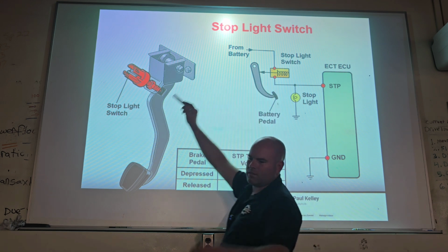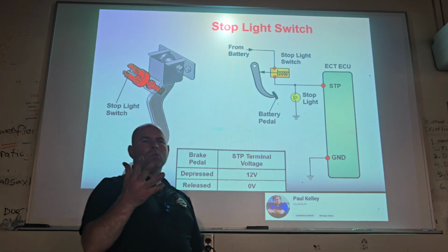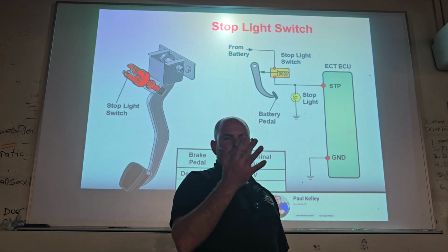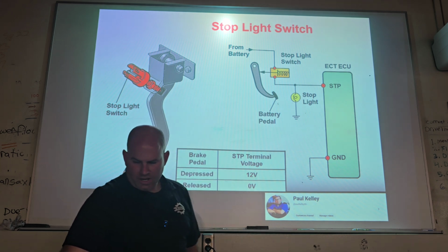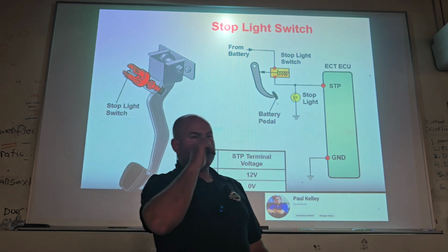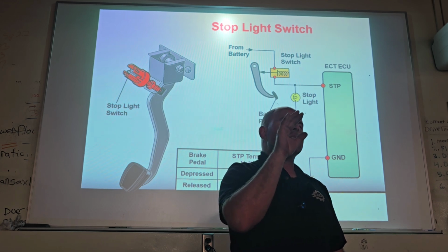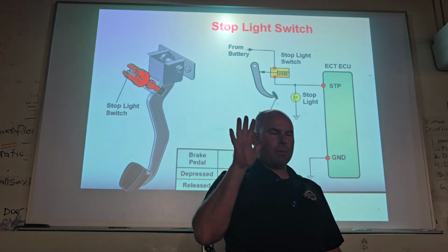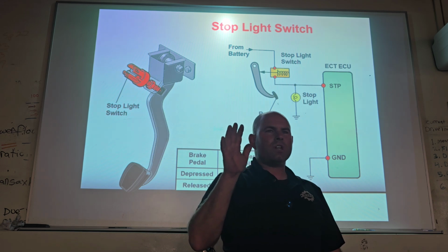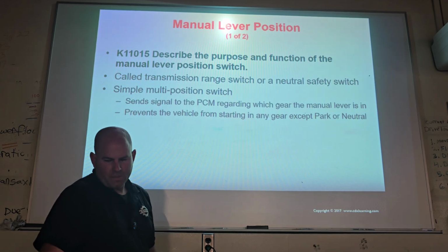So it's really easy to test. You could also just look at the scan tool and find brake pedal, applied and released, and you can just watch how it changes and get an idea if it's in the right area. You'll also get some that are adjusted right on the edge, where if you just lightly graze the brake pedal, it'll show them applied, and that could give you some of these weird torque converter concerns. Cool, so there's an adjustment for that.